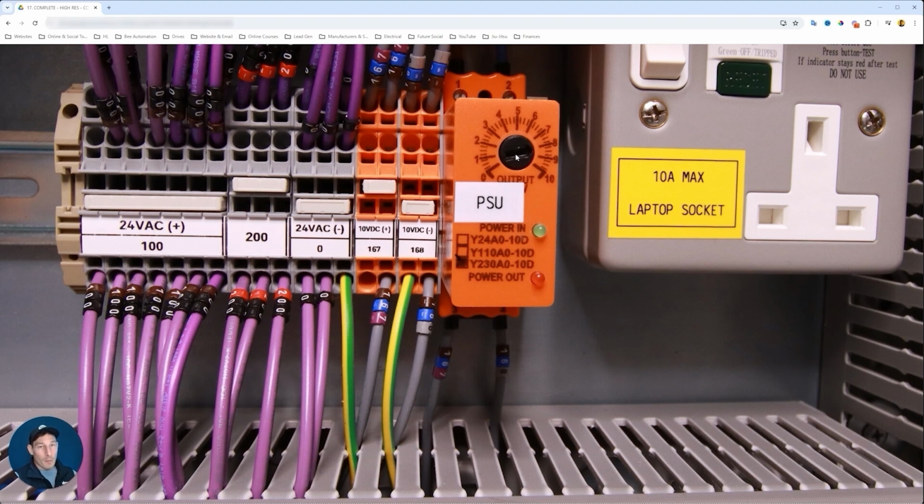So what we'll probably do is set this back to maybe 7 volts, 6 volts, which I think correlates to sort of 60, 70 degrees. So the boiler's not having to work so hard and burning lots of energy to get up to 90 degree heat. So we set that now to say 60 degrees C and 6 volts.